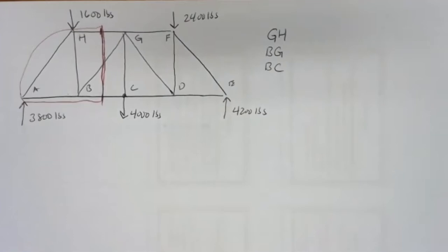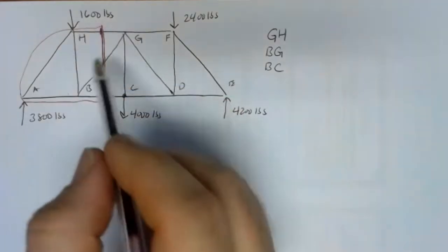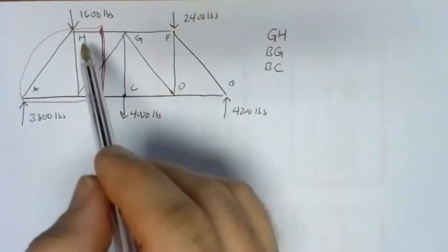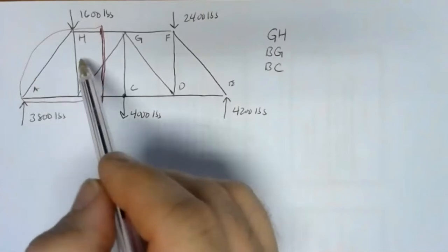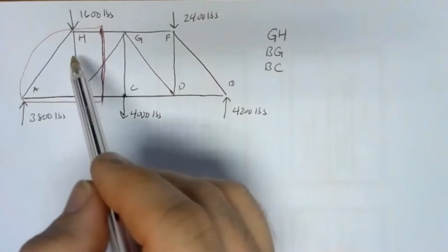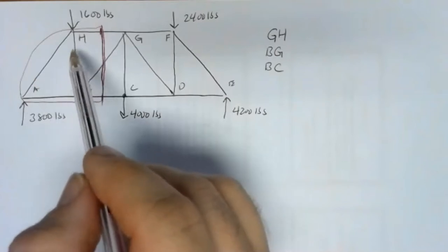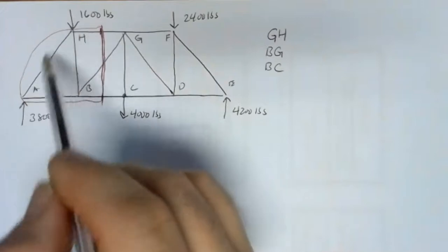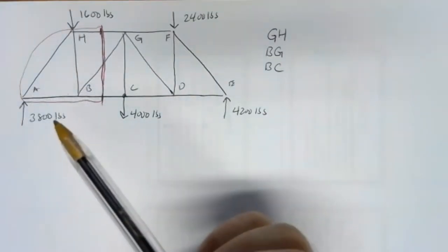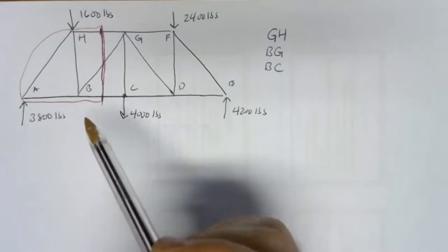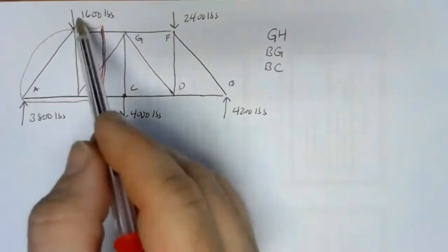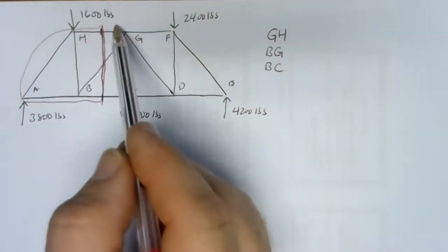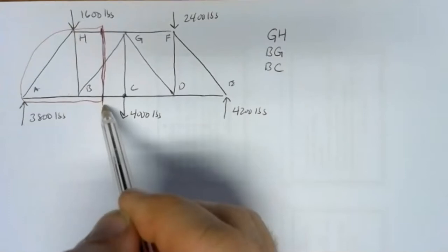Now here's where the magic happens. Remember that when we've got a system boundary, everything that goes on inside the system boundary, we really don't care about, as far as what kind of forces are there. Like, I don't care at all what member BH is doing, or what member AH is doing, or what member AB is doing. All that matters when we draw a system boundary is what touches the boundary, touches the edges, or what the boundary cuts through.